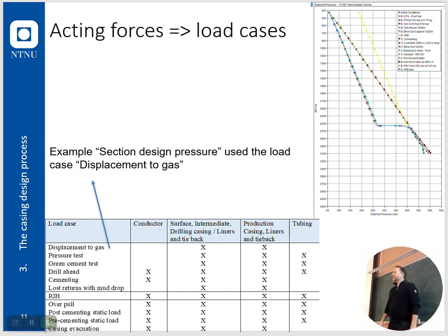And that's something to think about when it comes to integrity, because the weight particles in a poor quality mud are like sand, and this sand will make your casing completely stuck. It's just as good as any cement when it comes to integrity. Experience-wise, you cannot rely on that as an integrity base, but in reality, that's what it is.